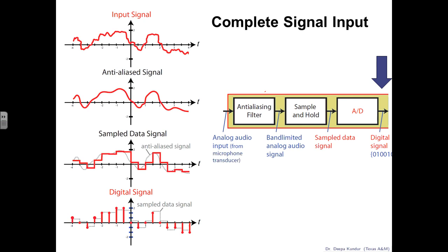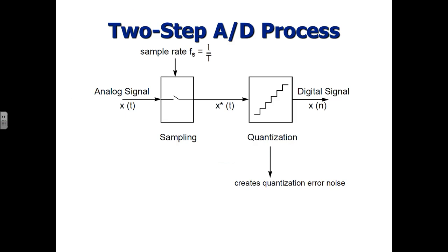The sample values are usually binary numbers, one for each sample period. And again, the sampling process is actually a two-stage process. First, we have to do the sampling, and we've been modeling that, taking the analog signal and turning it into digital samples. But we also have a quantization process where we're rounding off the voltage level of the input signal between quantized levels that we can turn into digital numbers.